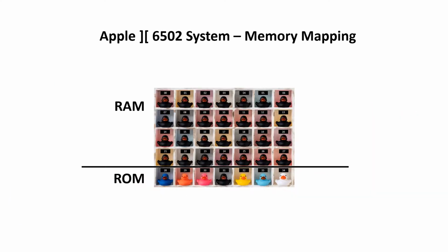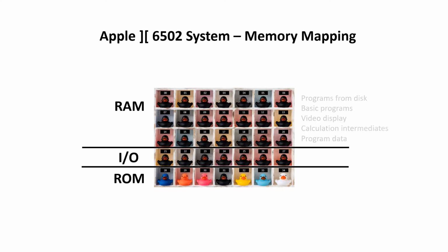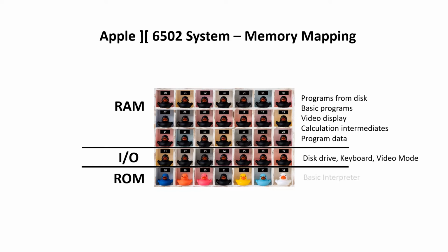Now the Apple II also connects to some other devices, such as the display, the disk drive, and the keyboard. For the display, the 6502 just reads and writes to RAM as normal, and some extra hardware in the background reads this RAM and sends this information to the display. As I said earlier, this is the main reason I want to use the 65C02, which allows the video circuitry to have access to the RAM.